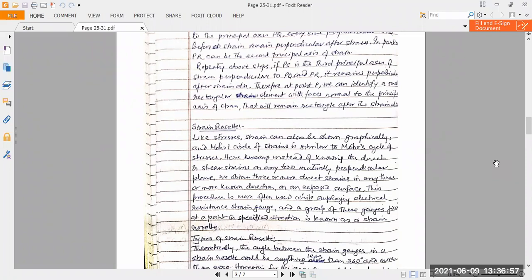Mohr's circle is a theory known as Mohr's circle. You can calculate all these stresses analytically, and you can also calculate all these stresses by drawing the length of the respective stresses as per a known scale selected by you yourself, and from the circle thus produced by a particular specific process, we can calculate from the circle itself different specified lengths: the value of sigma n or maximum stress acting on which angle, and value of tau n acting on the oblique plane, and what is the angular obliquity, and what is the maximum value of sigma n, and what is the maximum value of tau n, and over which angle or which plane it is acting.